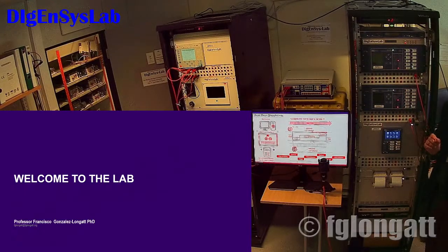In real time, what we are doing is solving the model step by step. In a computer, offline simulation, like DIgSILENT PowerFactory, you are also solving the model step by step. But when you are doing offline simulation, you don't care how much time you spend moving from one step to the next.